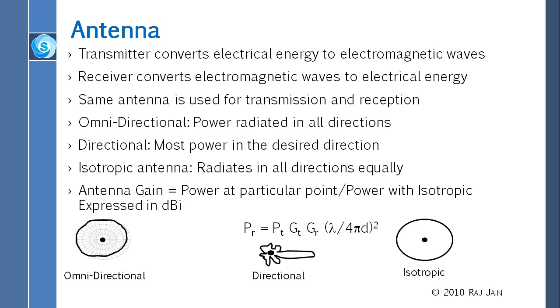So what that is that the GT is 7 dB. If you use that antenna compared to some other antenna, you will get 7 dB more power in the direction you want. Or actually there is another thing too. Even if you don't want directional, many antennas will, it's like resistance. Many antennas will just, you give them some power, most of it they will consume themselves, they will become hotter, they will convert that into heat, and very little will go into the air. Power can go either way, right? It can become heat or it can become electromagnetic waves. So a normal antenna will produce some amount of electromagnetic waves, but this 7 dB antenna will produce 7 dB more.